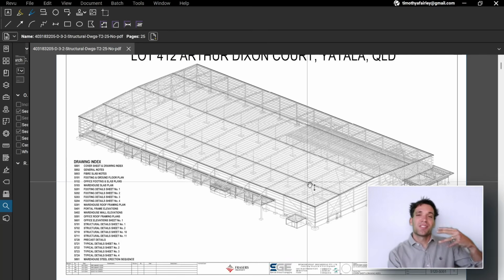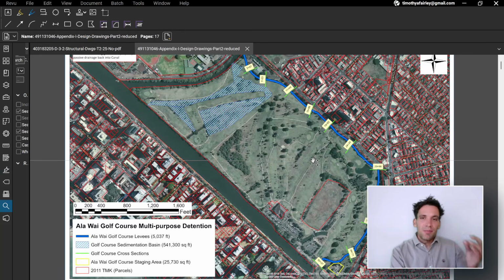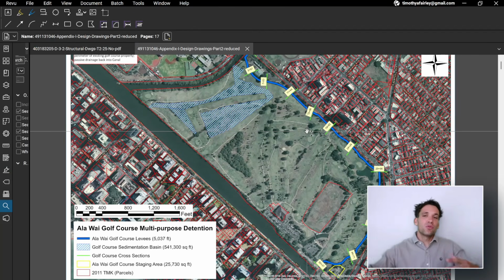You first need to establish a spatial overview and understanding of what you're actually building. And the way to do that is to start with some sort of system overview or isometric view. Anyone looking at this can instantly tell that we're building a warehouse, and you need zero technical experience to be able to do that. So typically on construction drawings, the first page, or it should be the first page of any set of plans, is an overview of the project.